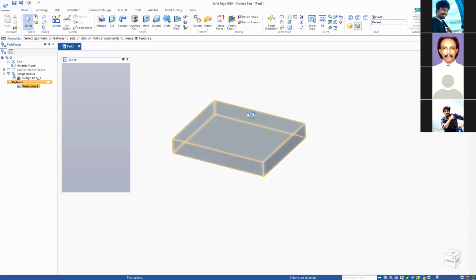Or I can open the sketch and then say length of, select the line, and then that line is equal to the other line. So then you don't want to dimension also, right? But if I want to tell the software that the width of this particular plate is 1/3 of the length, or maybe 2/3 of the length, some sort of a mathematical relationship, that way I will not be able to use the constraints or the relations.